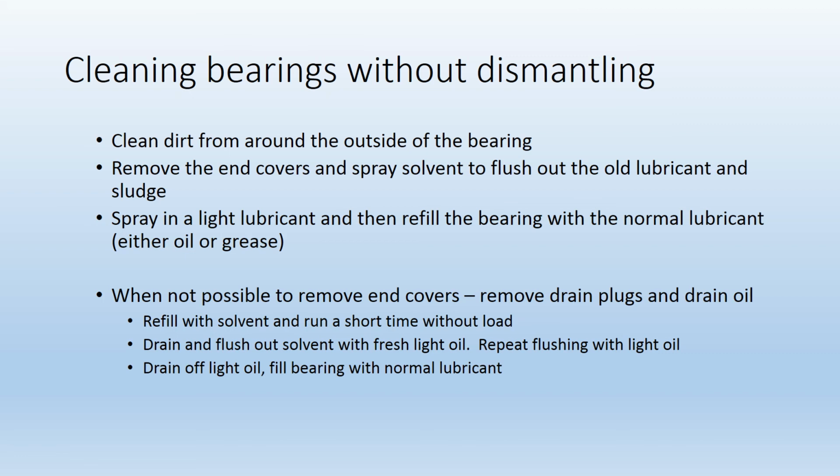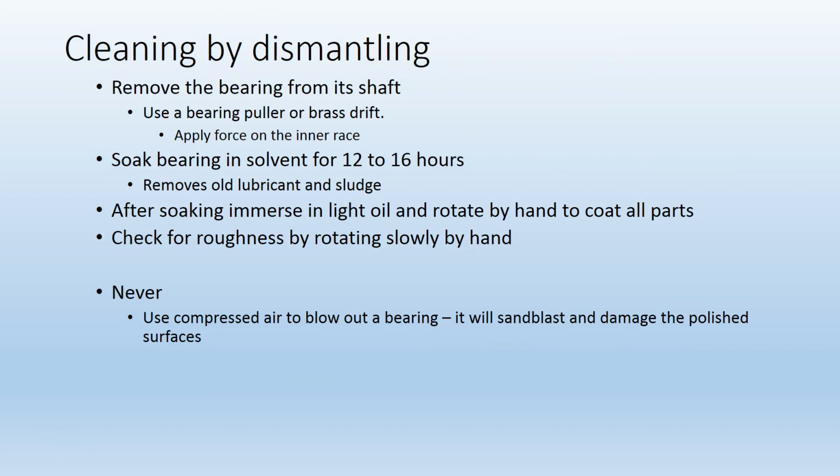And just keep doing this flushing with light oil until you're happy that all the solvent has been flushed out of the bearing. So then drain off your light oil, fill the bearing with your normal lubricant, and put it back in service. The best way to clean a bearing is by dismantling it.